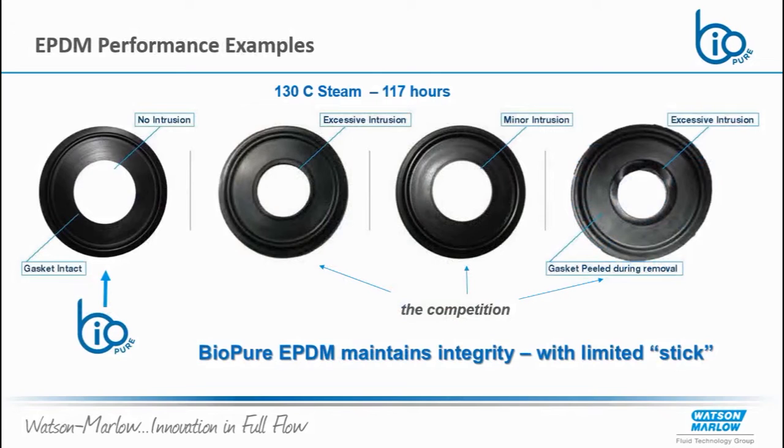Those factors, combined with that relative price, have really made EPDM the most commonly used choice for stainless steel or multi-use biopharm and pharmaceutical processes. That being said, not all EPDM is created equal. This picture shows our product on the left against 3 competitors' products, all after 117 hours at 130 degree steam exposure.